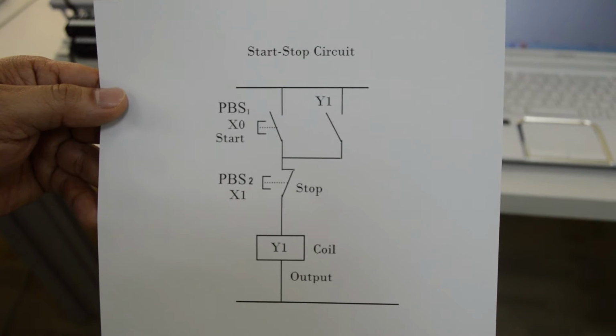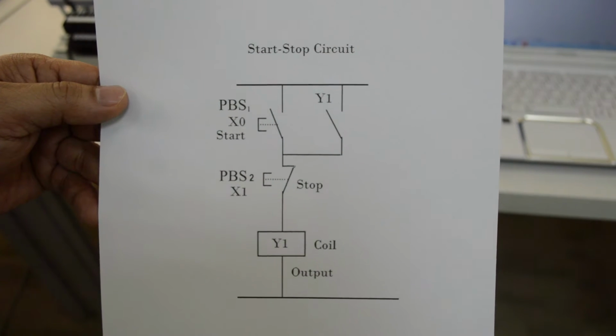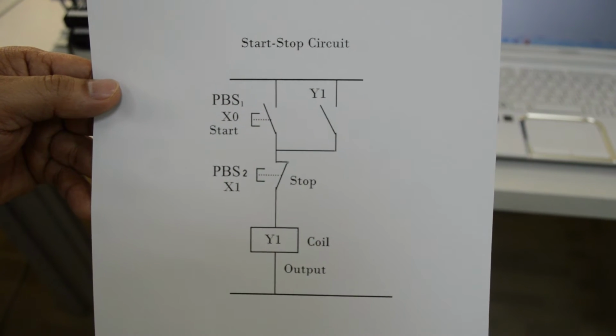Before that, we need to know how to use the programming platform so it's easier for us to perform such tasks. One important thing for you to have is your wiring diagram. So you should be aware of the devices connected with each input and output so that you can easily assign the devices respectively in your programming scheme. Here is the simple diagram we need to follow.